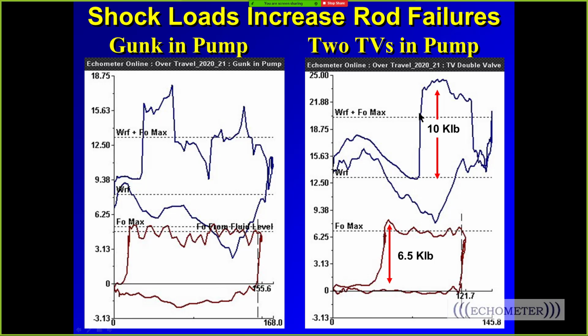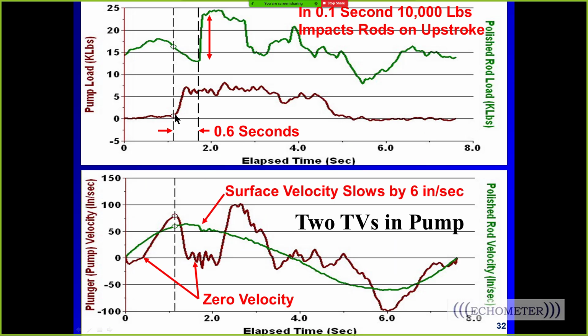And so here you can see this is a plot of pump load and polish rod load versus time. And it takes time for that force to move up the rod string. So the impact load occurs at this time, and in 6/10 of a second, it's felt at the surface because it took time for that force to move from the bottom of the well to the surface. And then it repeats: echo, echo, and so on.